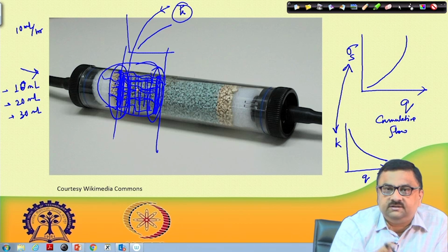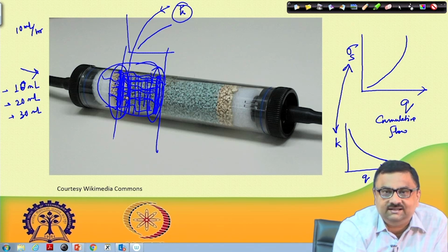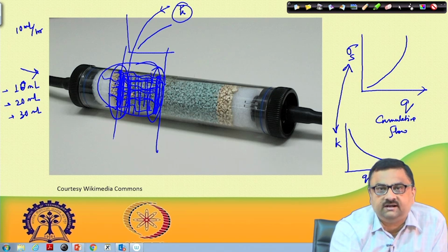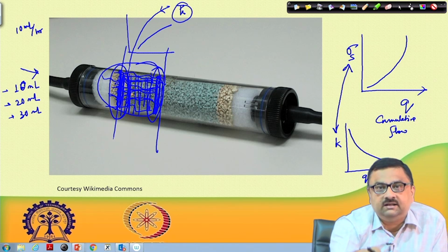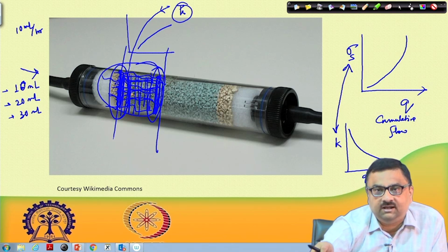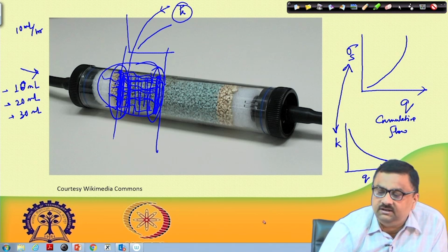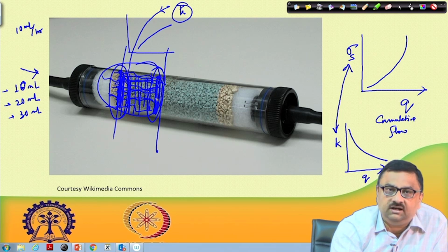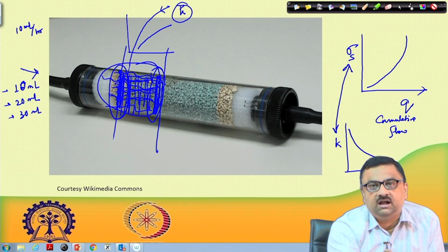Also, we have a bookkeeping formula that if this much deposition sigma s takes place at this location, then at the next location and the next, how much would be the concentration, how it has traveled. So, it will be the interplay of that bookkeeping equation and sigma s with respect to q through lambda, and then sigma s has to be related to the local permeability, which will also have a variation over length, and we can have an average permeability. Once we know all this information, then I can predict what would be the flow rate.